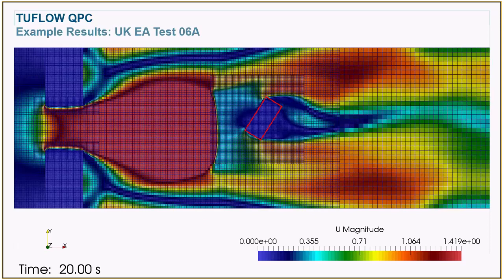The image shows the various levels of Quadtree refinement with 5 areas of differing grid resolution, which you could probably just about make out by eye, together with the mapped velocity. There's a number of hydraulic features within this model. Just upstream of the obstruction, we have a hydraulic jump, and that hydraulic jump propagates upstream as flow eases as the reservoir drains down. Downstream, we've got the obstruction wake and eddy shedding downstream of that obstruction.